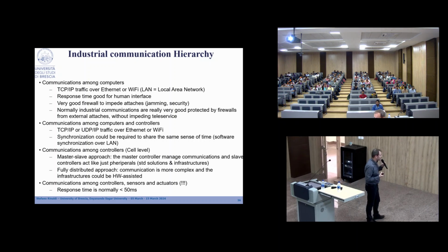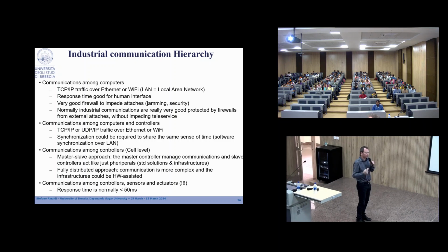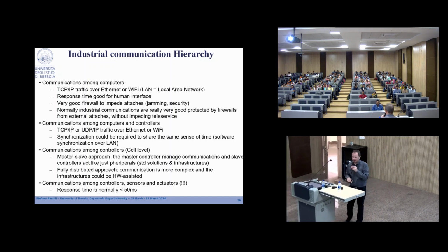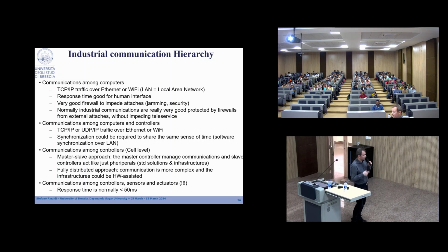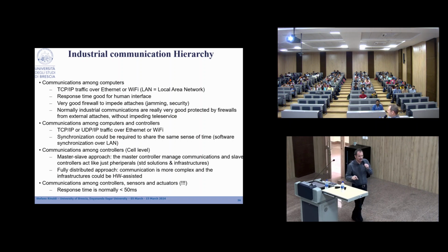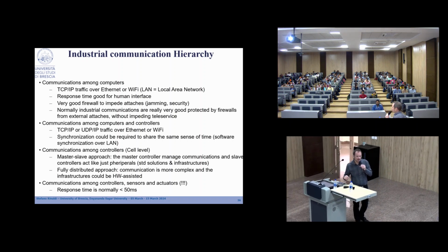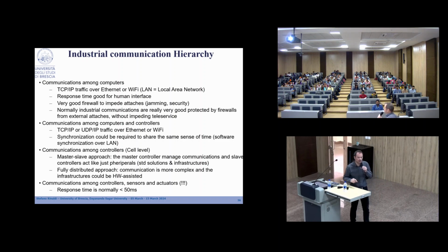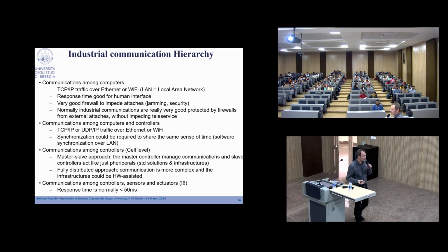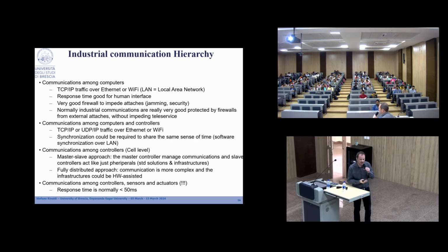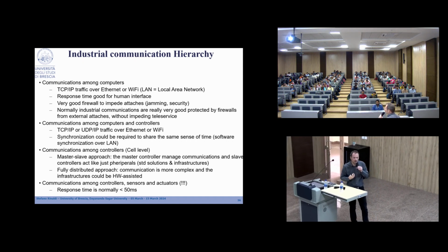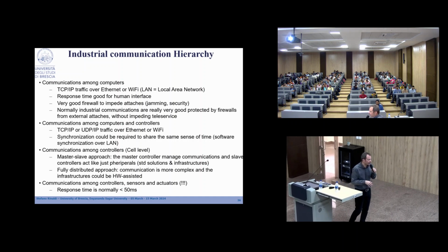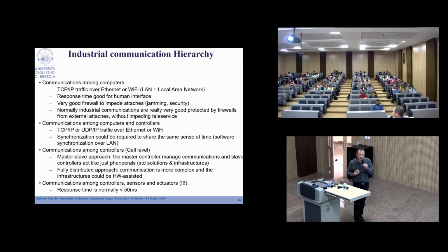The most strict communication system from the point of view of real-time communication is for sure the field bus, the lower layer of the communication. Because at this layer, the field bus layer, we need to transfer the information from the sensor to the controller. And if you remember the slide of a tank, the controller takes its decision on how to operate the actuator on the basis of information coming from the sensor.